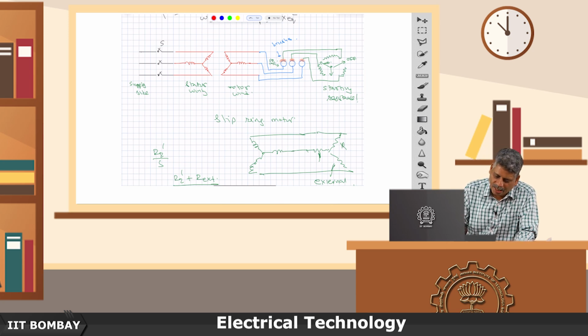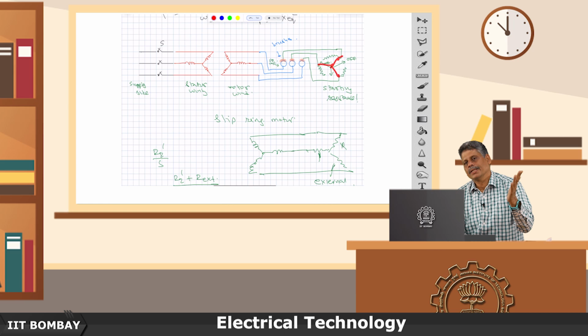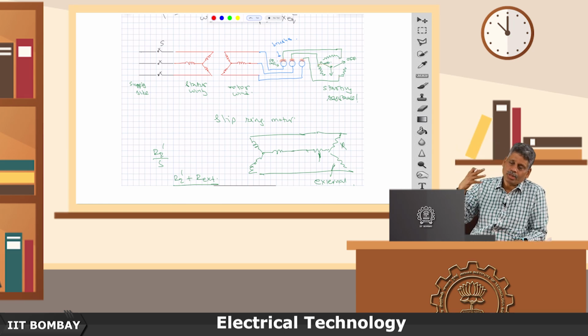And this is called a starter resistance, which is introduced. And then as I move this lever from here to here, finally this lever will come here, and the third lever will come here, and so you will get 3 levers like this, which means that these 3 resistances are completely cut off now, and the 3 windings are short circuited, and you will be able to run.